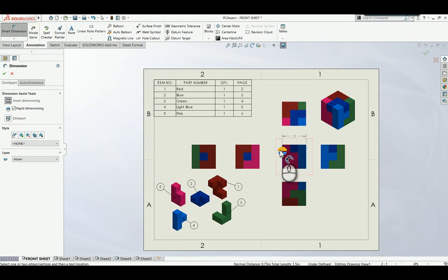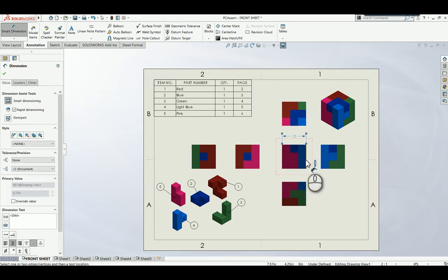When you get into drafting and standards, there are standards that dictate the distance from the object to the dimension, where dimensions are placed in relation to the object, all kinds of different stuff. SolidWorks has actually taken some of that off of our hands as the designer, and they've given us this nice little pie piece that correctly places them. So I'm going to choose the top to place my dimension between the front view and the top view. I'm going to do the same thing for a height dimension, and then also for the depth dimension.